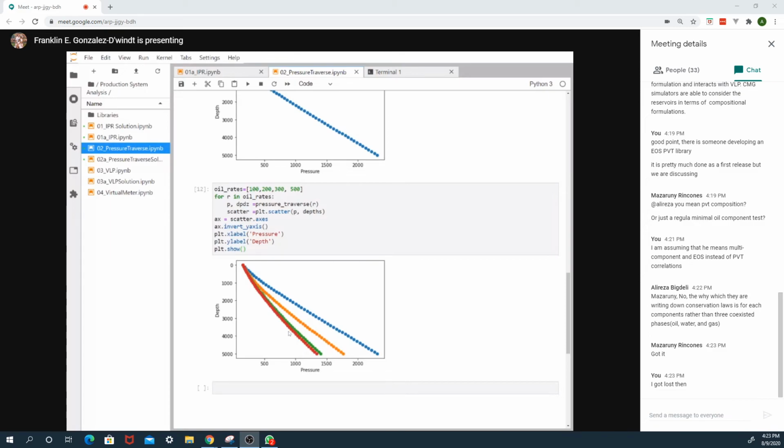We have water rate because I mentioned that the input on the correlation is in terms of rate, not in terms of water cut. I call the function we just created, and I extract my bottomhole pressure, the last value, and then I return the difference. So the output of this function is only the difference between the observed data and the calculated one.